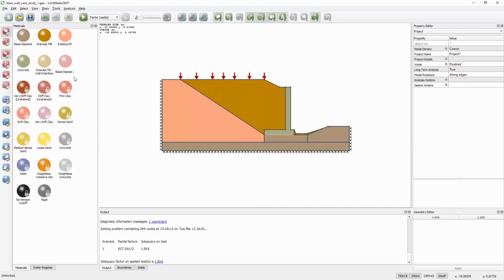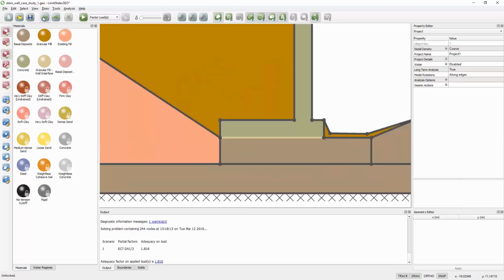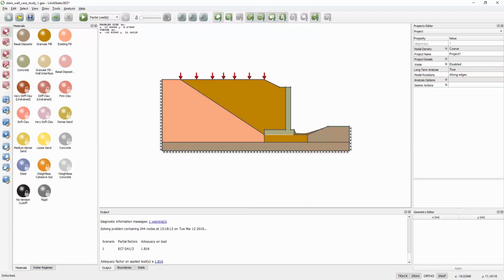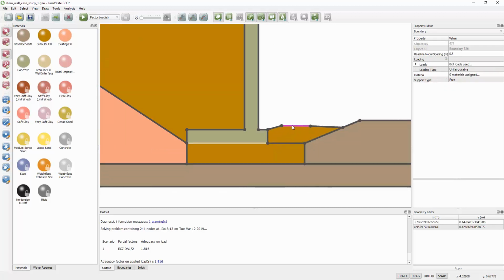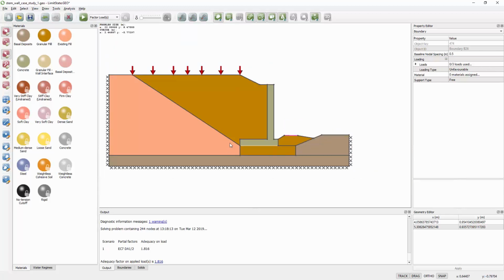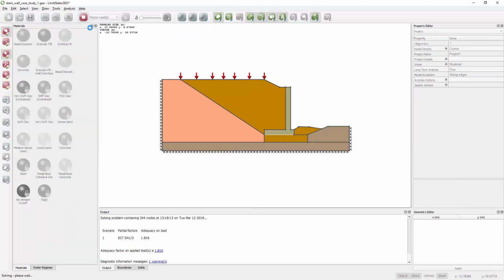That, of course, again means excavating material and replacing it, or bringing in stronger fill. So if I undo those two changes, one other thing we can look at is perhaps suppressing the failure under there by increasing the surcharge on this side. So what I've got here is a kind of truncated block of soil, which I'm just going to push up. And if we put a bit more weight there, that will hopefully suppress that mechanism.